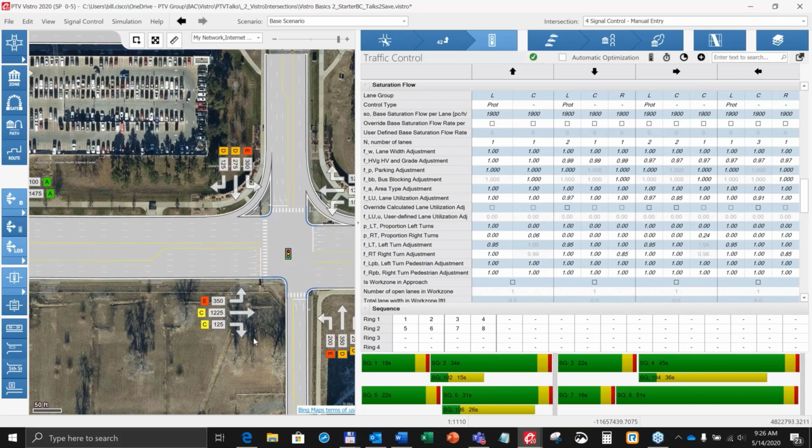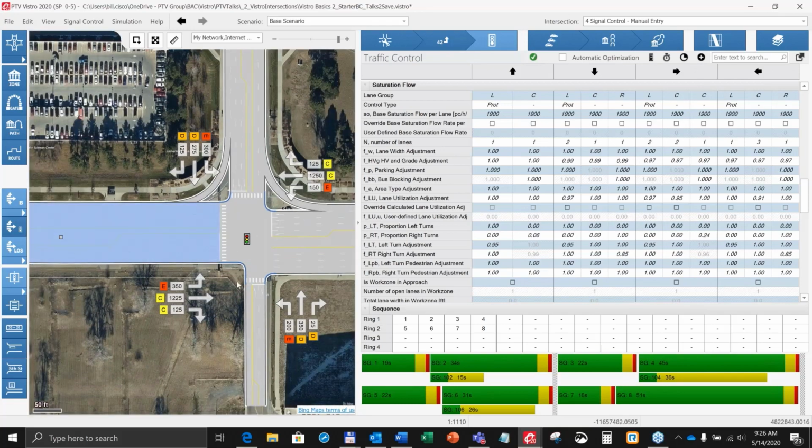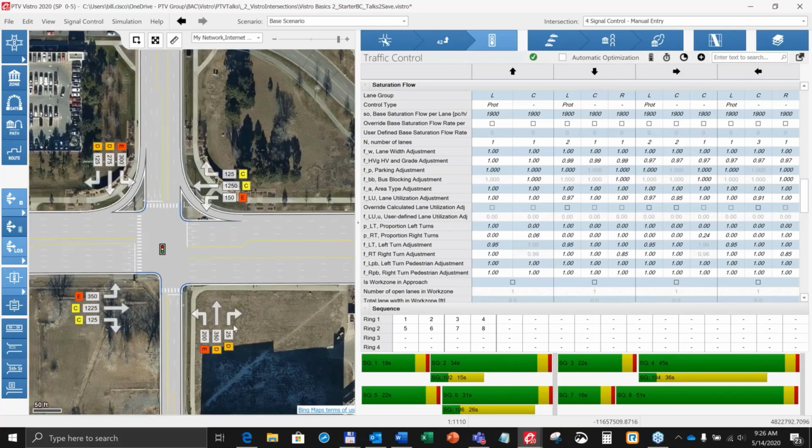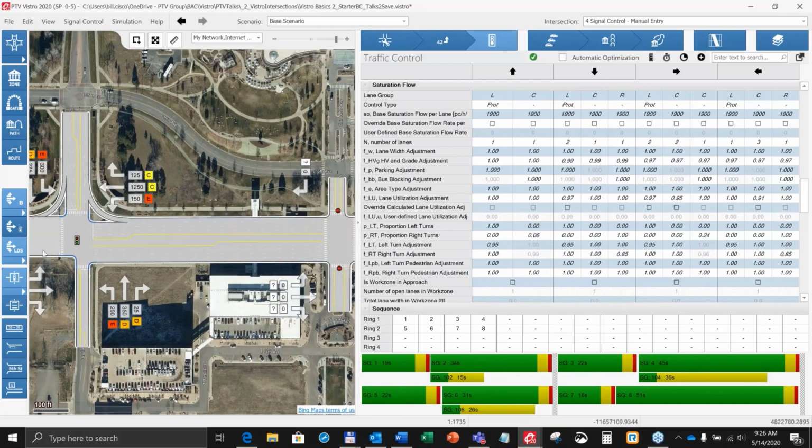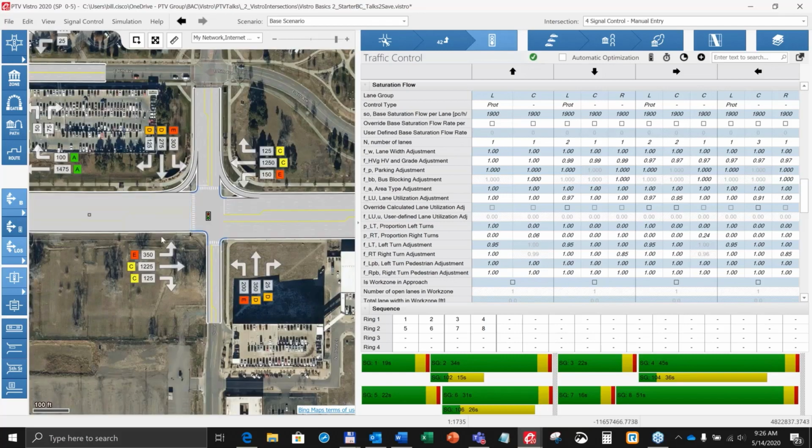I like to use an example of special cases. This is not a freeway on-ramp, but sometimes if you have a freeway on-ramp, vehicles start pre-positioning themselves ahead of time. Actually, it would be more like the downstream intersection. If this were a freeway on-ramp, my through movements at the upstream signal may already begin to pre-position to show more of my throughs in the rightmost lane.